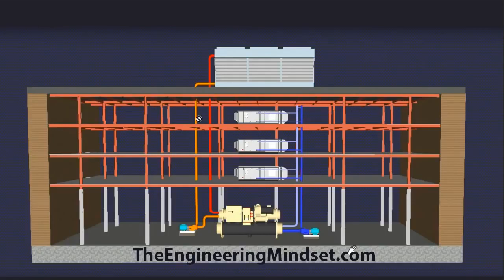The air within this space needs to be conditioned, so there's a fan inside there which we'll also be looking at, and that's going to suck the air from the office into the AHU, and that will then cool it down and may heat it, it may humidify it, and it's also going to filter it and check that there's enough fresh air in that space as well. And then that air is going to be pushed out onto the floors through the ductwork. I haven't shown the ductwork on this, but you'll see an example shortly, and that's distributed around the office.